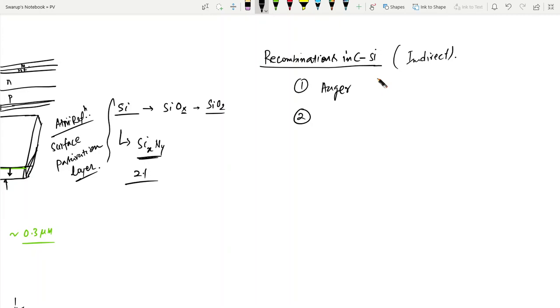But on the surface where we are cutting it, sawing it off, or on top of the wafer, there are surface dangling bonds, and because of that there are defects, which we cannot avoid. Even in a single crystal, the surfaces are full of defects because of the dangling bonds present on the surface. Now, whenever we have this kind of defect, which recombination takes place more?